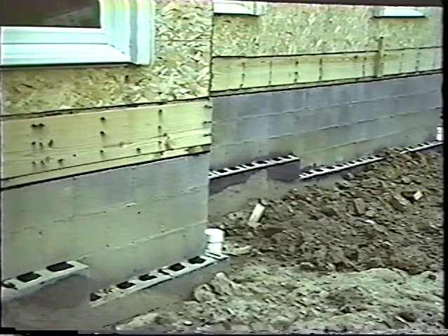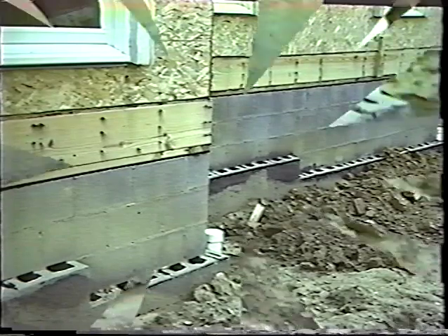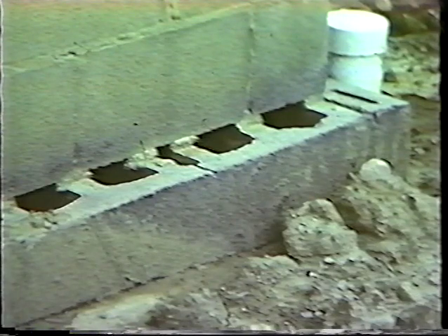Masonry must be supported on adequate foundations. Foundations such as this are never appropriate. The top course of masonry foundation walls must be solid units or hollow units filled with grout so the brick has full bearing. The hollow units on this project will be filled with mortar or grout.